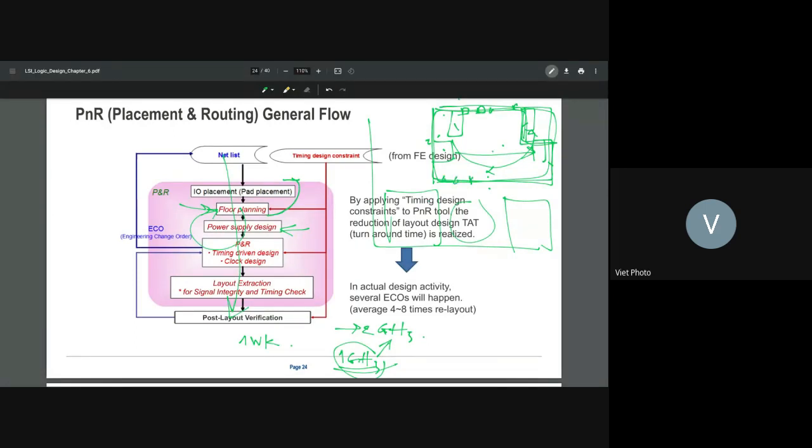But when you put the input here, it affects the way we put the macros inside, because if the pin goes here, then you have to move this macro down. So the first thing to do is to negotiate the IO locations regarding the other blocks.